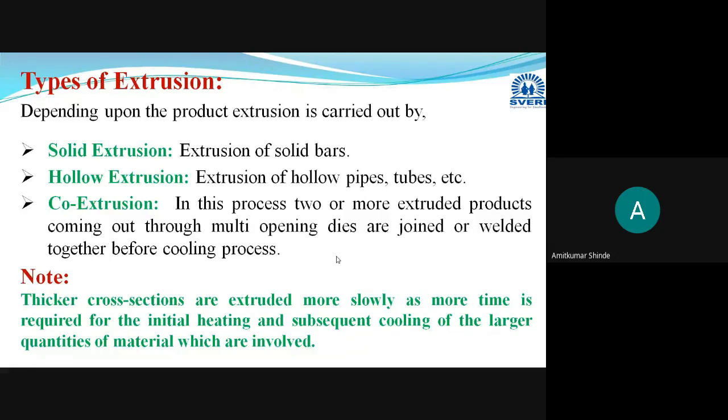Here again I have collected one important point, and I have written it in the note. You can add this while writing your answers. Thicker cross sections are extruded more slowly, as more time is required for initial heating and subsequent cooling of the larger quantities of material.